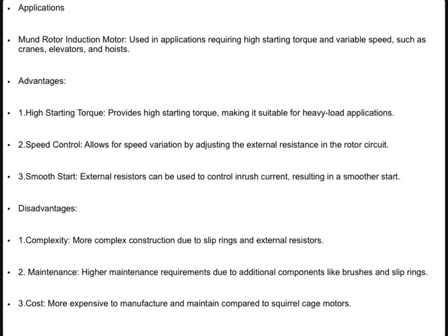Disadvantages. 1. Complexity. More complex construction due to slip rings and external resistors. 2. Maintenance. Higher maintenance requirements due to additional components like brushes and slip rings. 3. Cost. More expensive to manufacture and maintain compared to a squirrel cage motor.